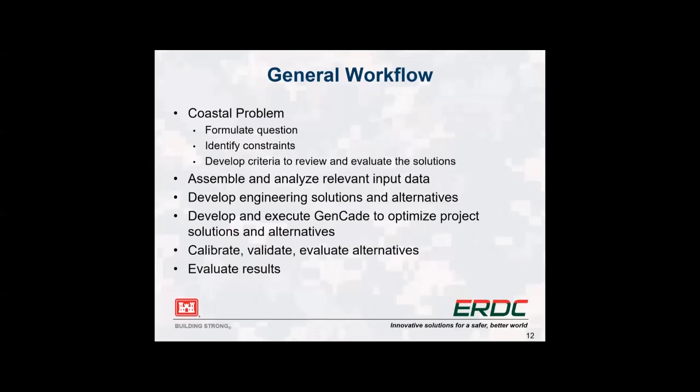So typically when you're using GenCade, you come up with what your alternatives would be, and see what your constraints are as far as what you could feasibly construct or what your solution will be. Then get your data together. You want to get as many historical shorelines as you can, hindcast data from WIS, and also any interventions that were done in the past, so any structure construction, beach nourishment or dredging.